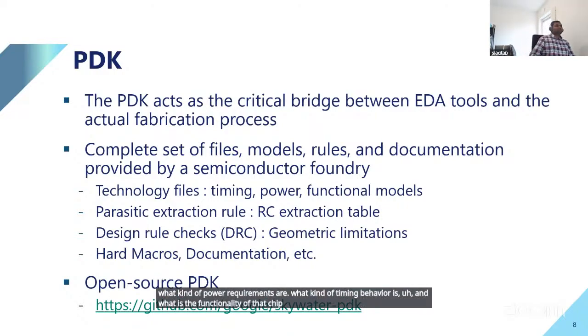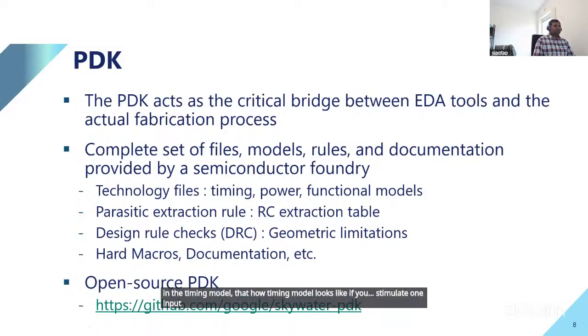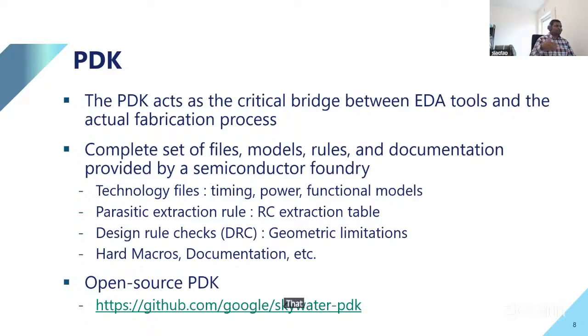If I just take an AND gate, for example, they will tell me the length and width of that AND gate. Of course, it's made up of transistors. Then in the timing model, they will tell me how much time it takes, if you stimulate one input of an AND gate, for that stimulus to be reflected on the output.